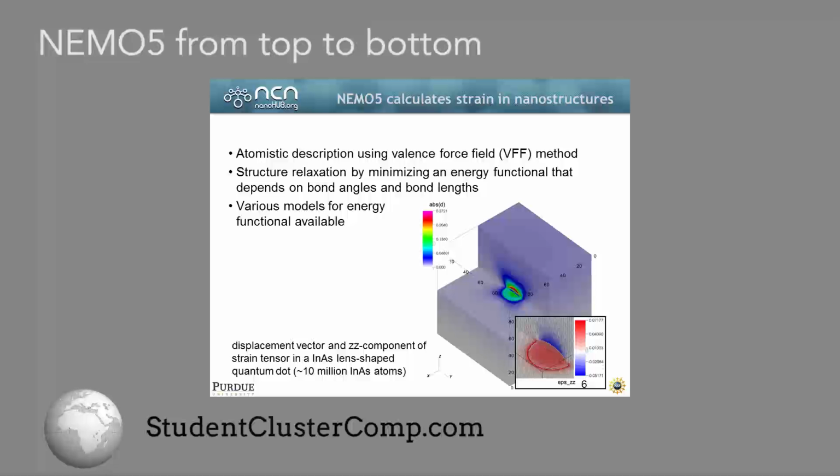The idea here is that the dot is made of a different material than the large block. And so the electrical properties of this whole system are going to change when all the atoms are in their relaxed position. So when these devices are fabricated, you essentially have to find what configuration gives the minimum energy for this structure.